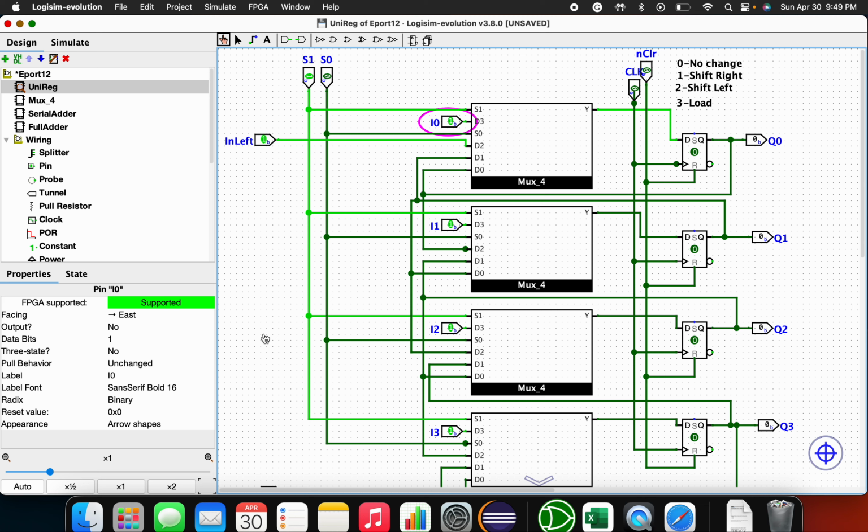First one is a register. A register is just something that holds memory. A shift register is something that stores and shifts binary data, and it's made out of flip-flops with the output of one leading into the input of the next. And this is going to be loaded serially, as in every single bit is going to be shuffled either left or right, and then depending on the design of the circuit, it could be filled in, and it could also loop back around.